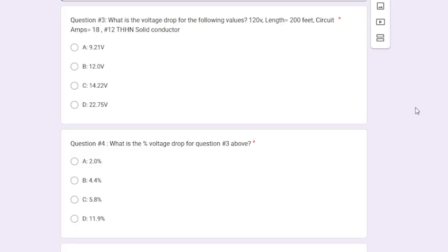Just note, again, this is why I change it, to remind you the voltages can change in the exam. In the exam we're only looking at single phase, so it'll be either 120 or 240. But notice question 3, since you'll need it for question 4, is now 120 volt. Don't divide it by 240 just because we did the last one with 240.